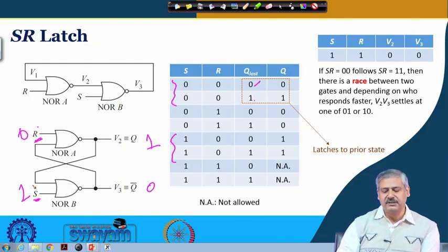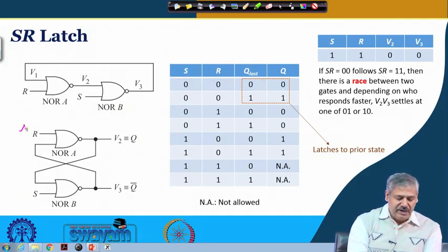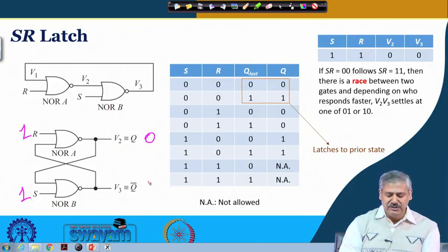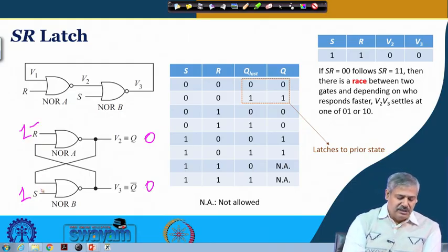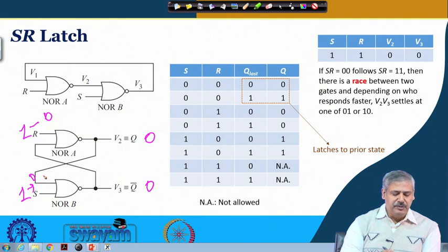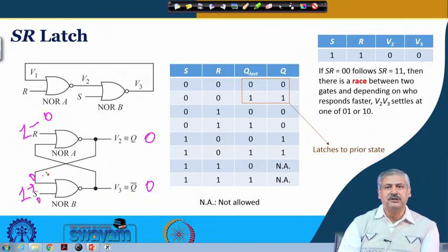Okay. Is it fine? Now, what would have happened if 1 1 was presented here? The output would have been 0 0, which is fine. As such there is no ambiguity about it. But after 1 1, if you try to put it into the latching state, where the past value would be latched, and then you put 0 0, both inputs are now non-enforcing.